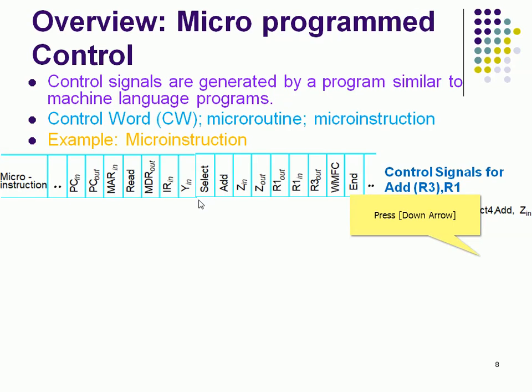Due to that PC out, the other variable B, you can recall the ALU circuit. The ALU has two inputs, A and B, right? B is connected directly to the bus, and A is connected via a mux through the select 4 and Y register. So the select 4 data 4 will enter into the ALU, then B will receive the program counter value from the bus.